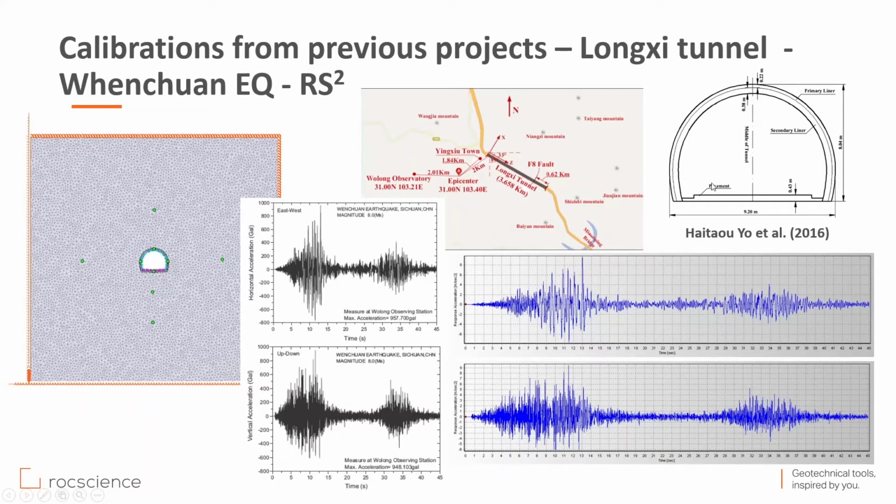What is important is the rock support system used, mainly at this area near the main fault. Shotcrete layers and also the pavement, a concrete layer with a thickness of 43 centimeters, were used.